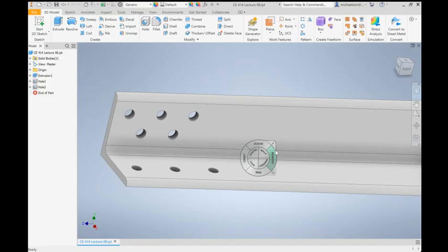It did. I think I was a little bit confused because in the homeworks that we've done, there were a few more bolts, so maybe there was some uncertainty as to what exactly line it was going to take. Whereas this only has a total of 8 bolts in the entire member, and only 3 of them are on the lead line, so it makes sense that you could get it more quickly. I think it might have been homework 2.2 that had a lot of bolts, and a lot of bolts on the lead line. So there were all sorts of different diagonal paths that you could consider. Whereas this one, there just aren't that many.